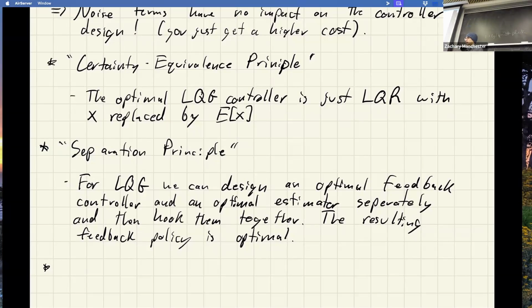inputs. A good classic example of this that I got as a grad student in a stochastic control class was, assume you've got, I don't know, your double integrator problem or whatever, the sliding brick, or even just a thing where you have velocity inputs. So it's a linear system and it's on the line. But your measurements, you only get to measure the absolute value of the position. So the gist is now you don't know if you're on the left or the right of the origin. So how do you figure that out? I have a control input, I have the force input, I can push it left or right.